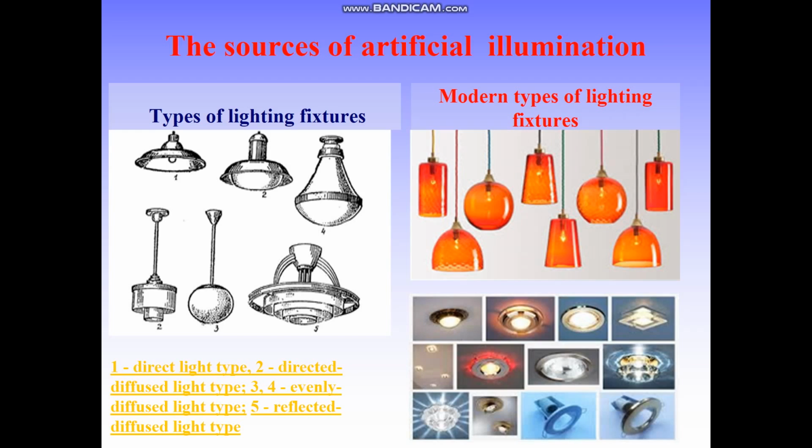The bright source of light causes fatigue of eyes and adversely influences the nervous system, therefore the work capacity is reduced. The lamps of reflected light direct the most part of the light flux to the ceiling, and when the light is reflected downwards, it is the most appropriate type of lamps in the hygienic sense because of uniform, soft, and pleasant lighting for normal vision.